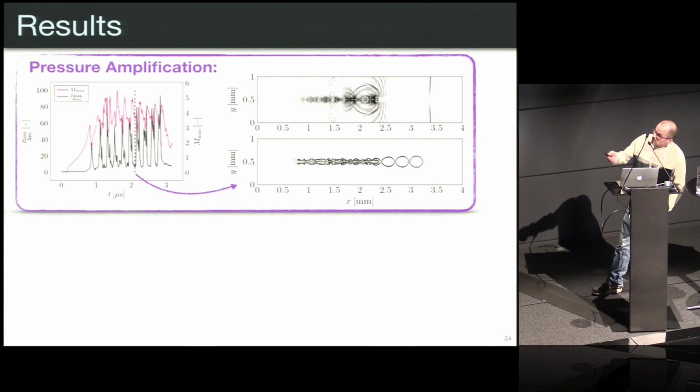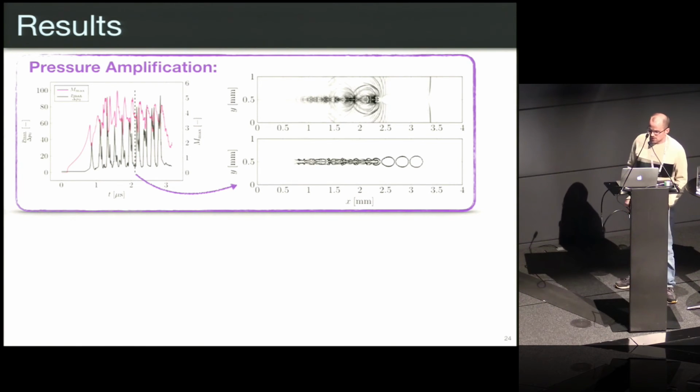On the right side, we show some Schlieren visualizations on the XY plane, which are through the center of the domain. The top image shows the wave structure using the pressure gradients, where we can still see the leading shock wave. And the bottom image shows the interfaces, where we can also see the numerical diffusion due to the diffusive interface method we use.